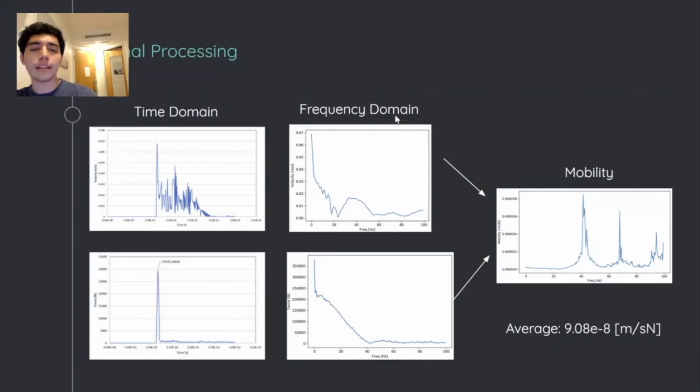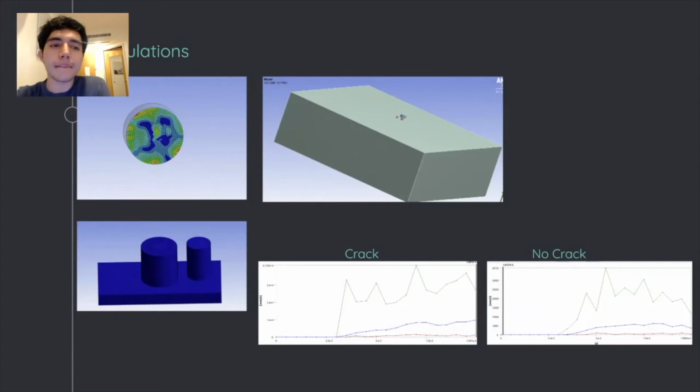And then we did a velocity profile on the face of the transducer to simulate what the geophone would get in the voltage data. And we also did a stress analysis on the puck to get what force we were hitting with. By using these two things, we were able to calculate other things in the future. You can see here how the faces of the different shapes look, how the impact is performed after giving an initial condition, and how velocity looks for a crack and no crack.